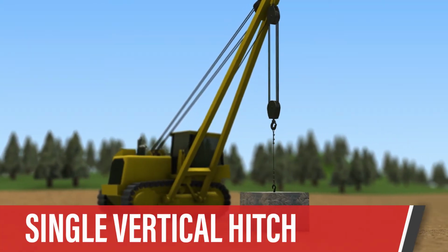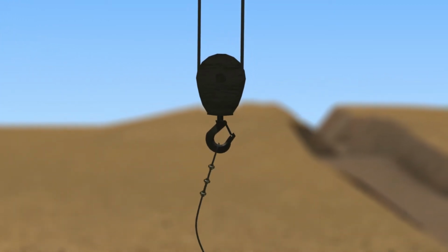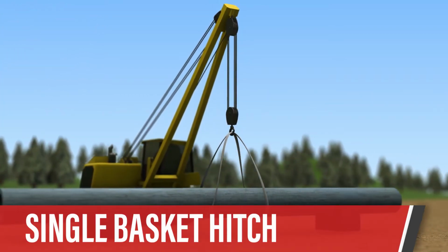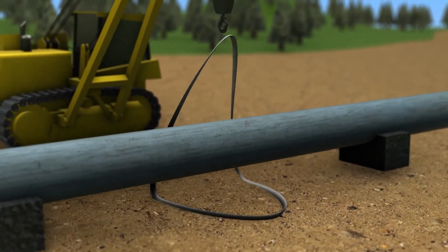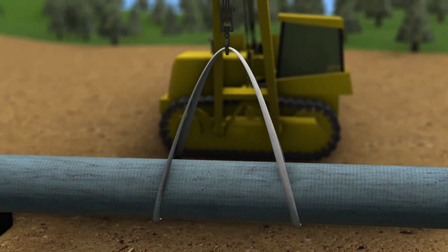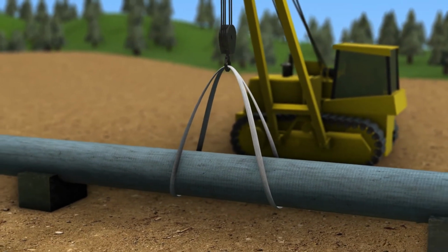Single vertical hitch. Single vertical hitches are used for basic loads and consist of a single leg of sling material with a hook and an eye at each end. Single basket hitch. In single basket hitches, a single length of sling material is passed through a load, and both ends of the sling attached to the main hook. If the load might tilt or slide out of the hitch, a single basket hitch is unsuitable.